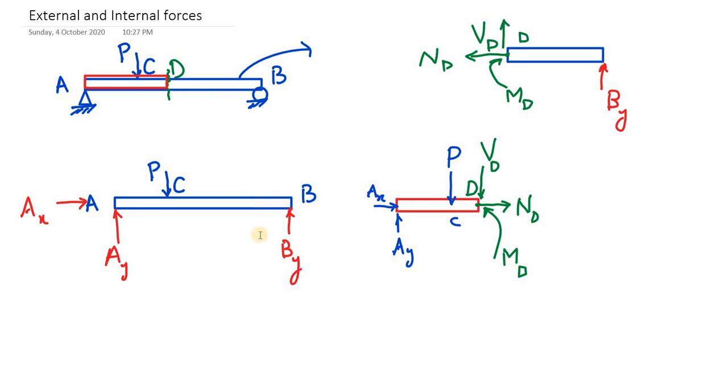A very important thing to keep in mind is that, as far as external forces are concerned, all the forces shown over here are the forces externally acting on this beam. For external forces, you can draw them initially, when you are just starting the free body diagram, either upward or downward, it doesn't matter. You can show this rightward or leftward.